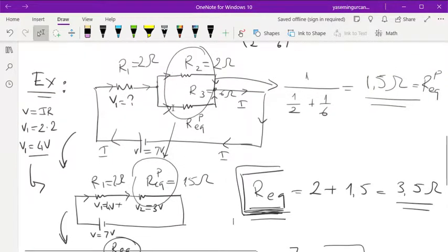And once again, what did we say about the parallel connection? Voltage is the same on both. And if we say 3 volt is on this parallel part of the circuit, it basically means that if you connect a voltmeter on R3, what you would read is 3 volt here. And if you connect the voltmeter and read the voltage on R2, you would again read 3 volt here.